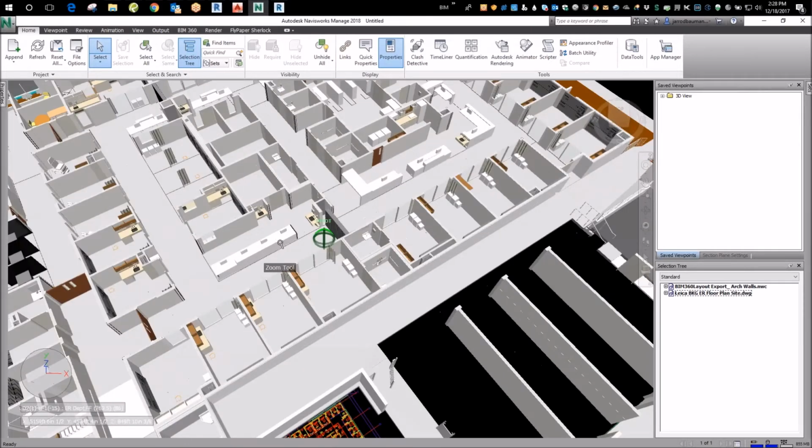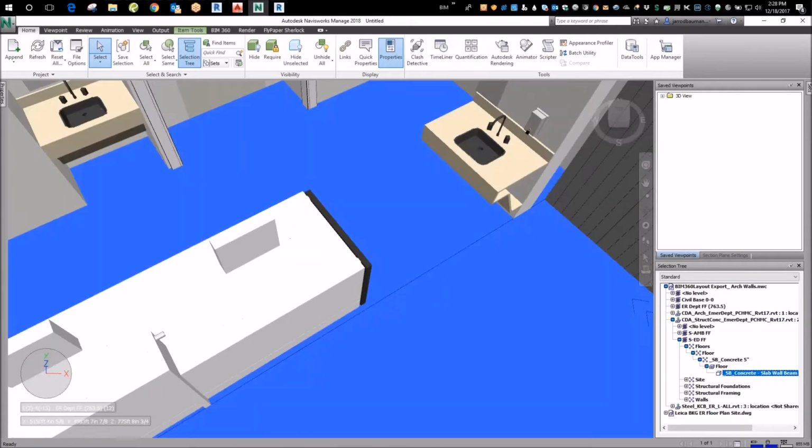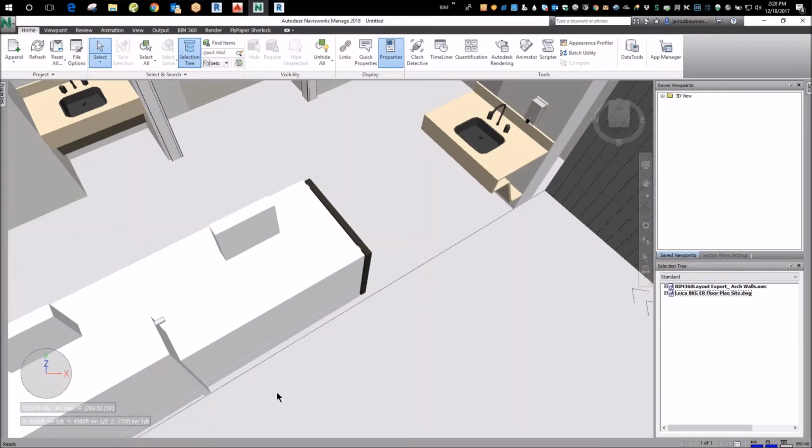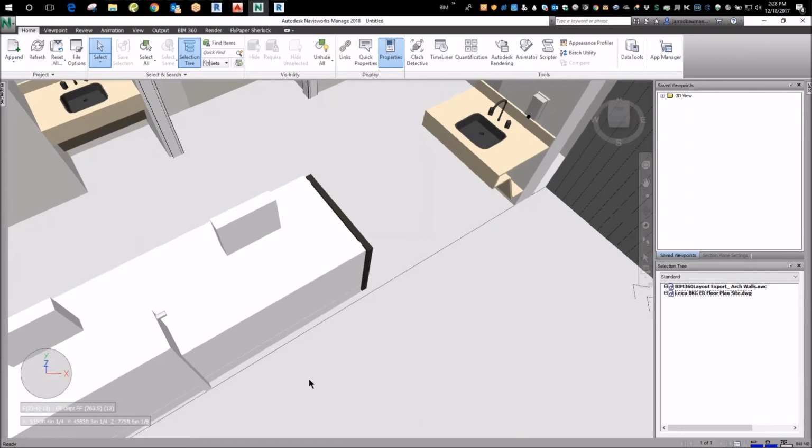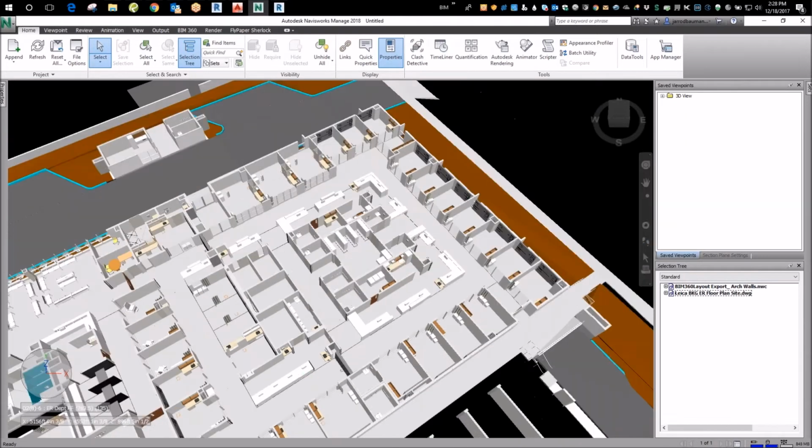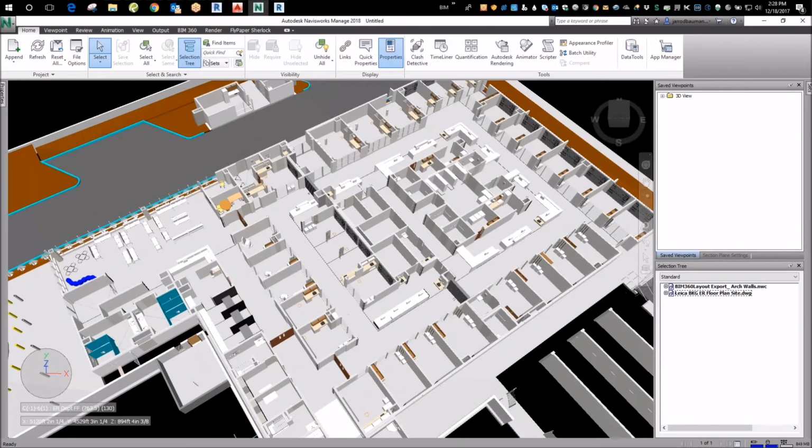So this model, if I zoom in here and I use my coordinate readout, which you guys might not have, you'll notice my coordinates right here. I'm around right where my eye is now, and Navis is at 775 feet. Finished floor is found on our documents, right? Civil plans show us finished floor elevation. So I'm going to give you that. Finished floor elevation of this model is 763.5. So that's 763 feet, 6 inches.